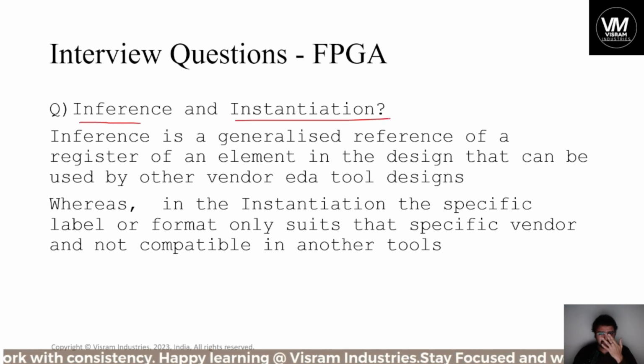And what is inference and instantiation? This is a basic application of FPGA writings. For example, you are writing a Verilog HDL or VHDL code with some inference. Inference is nothing but a generic terminology or generic representation of the design that can be widely applied over different EDA vendor tools. For example, if you have been designing in Xilinx Vivado and you have inferred a design, that design can be easily taken into another vendor tool like Intel Quartus Prime, and you can work with the same design.